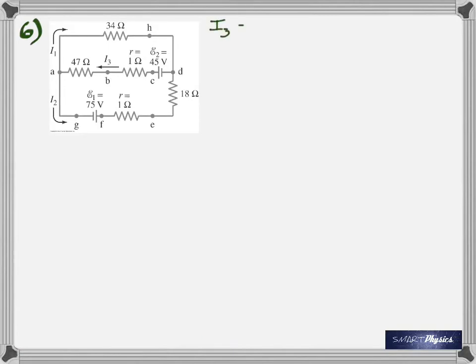Now this is where you have to apply Kirchhoff's laws, and when you apply Kirchhoff's laws, you have to carefully look at the circuit and decide. KCL is Kirchhoff's current law, according to which if you look at this diagram, you have I1 and I2 flowing away, I3 is coming into this junction. Therefore, I3 is equal to I1 plus I2.